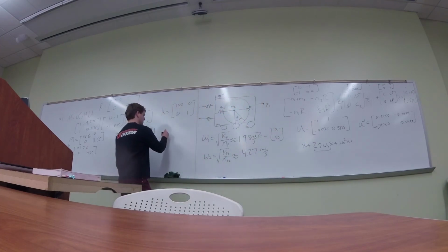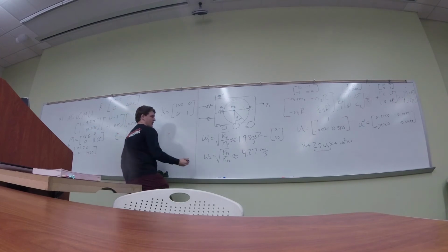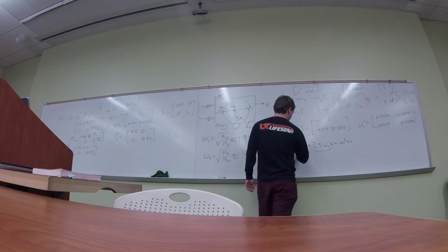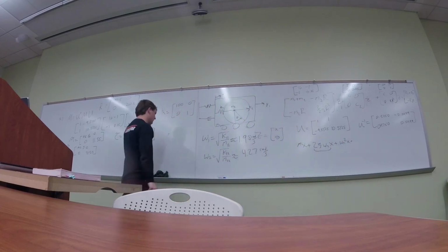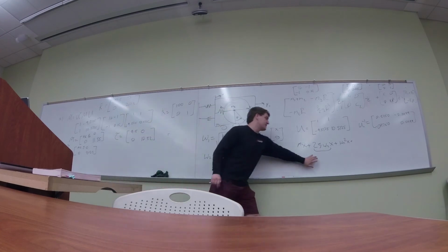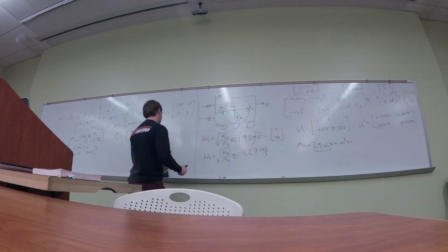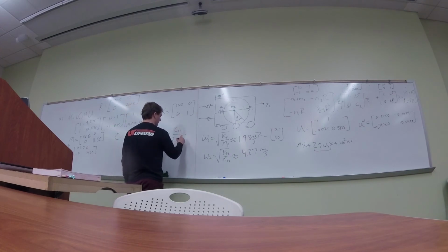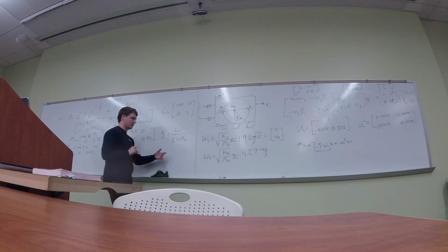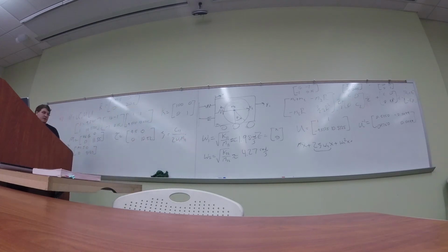So you have some mass here, and you have to divide that mass through to get into the actual form you're looking for. So zeta is going to be equal to C11 divided by 2 omega 1 times M11. And that's how you're going to get that solution.